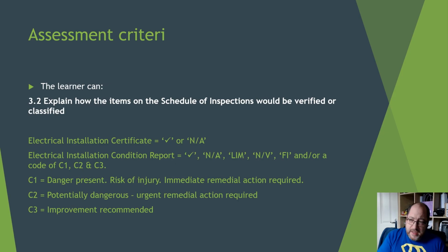If it's well maintained, if it's not been touched, the guidance note does say you may not need to do this test, so it may not need to be verified. It's not a limitation, and it's not applicable, it's just not verified. That's why we have the ability to use not verified. If your certificate, like an NIC or whatever, doesn't have that, well, it's just a bit crap really, isn't it?